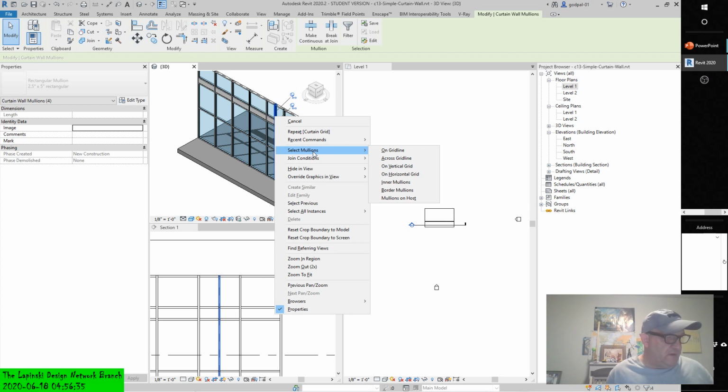So select the vertical grid line you created in step 1. You may need to press the Tab key until you see the dashed line indicating the curtain grid. Notice that the grid extends the entire height of the wall. With the curtain grid selected, click the Add Remove Segments button.